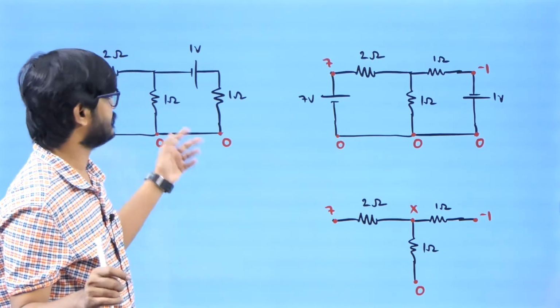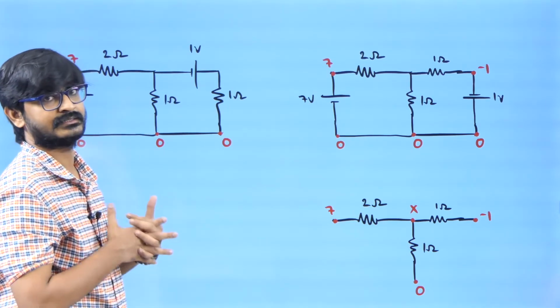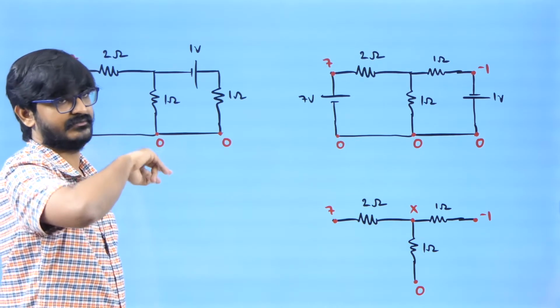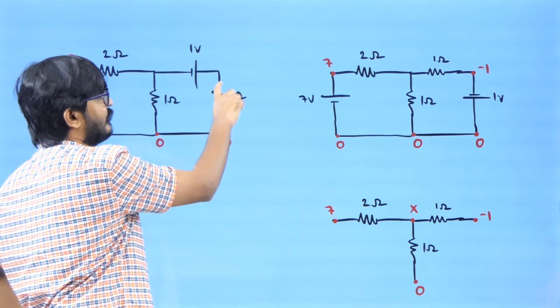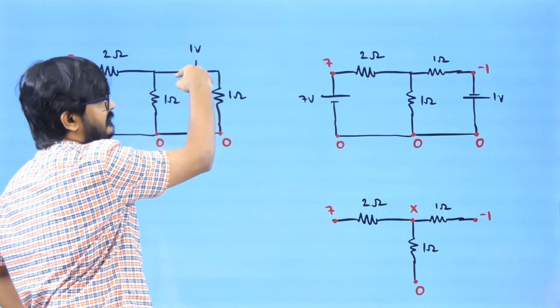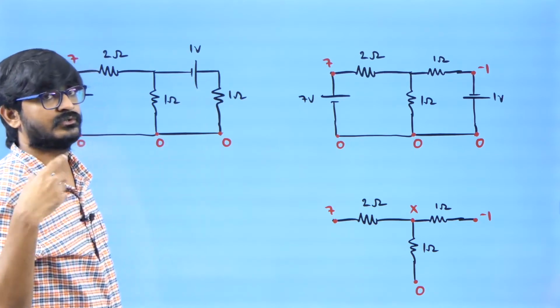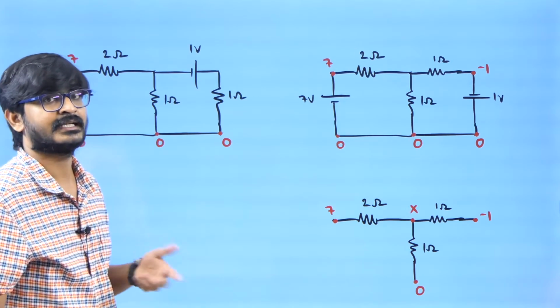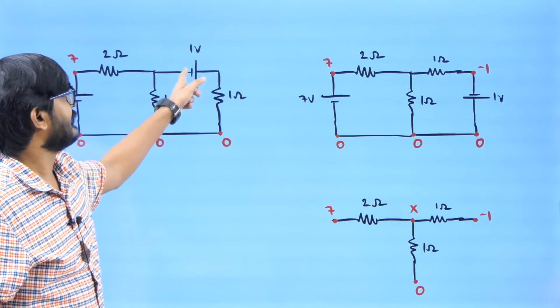Now, okay, so this is the question, and in this question you need to find what is the current in the other resistors. Now how many loops can you see? You can see 2 loops like previously, right? So when I write loop equation, it doesn't matter whether I into R will come first or this one will come first. So even if I keep it here and if I keep the resistor here, still the loop equation will look same. So I know when the 2 loop equations look same, the result has to look same about currents, right? So what I can do, I can interchange these 2.